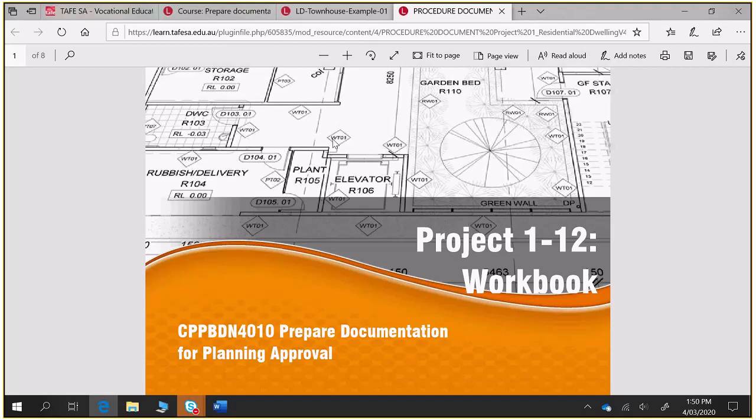That's not always the approach you take for everything, because typically if there are construction details, tie downs, all that sort of stuff, you're going to make that specific to your timber framing, or if there's something specific to your deck, you'll make that specific to your deck. You'll have in your bushfire notes things like timber to meet Table F from AS 3959, and then framing and stumps to be non-combustible. So you have that general information.